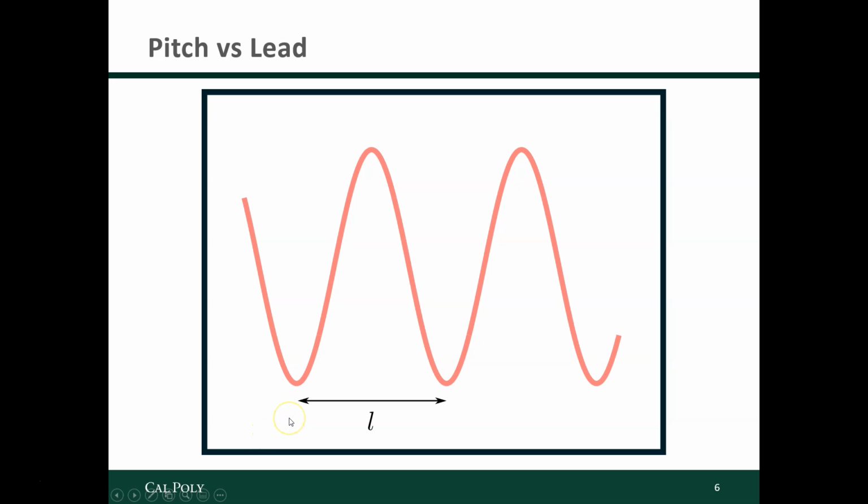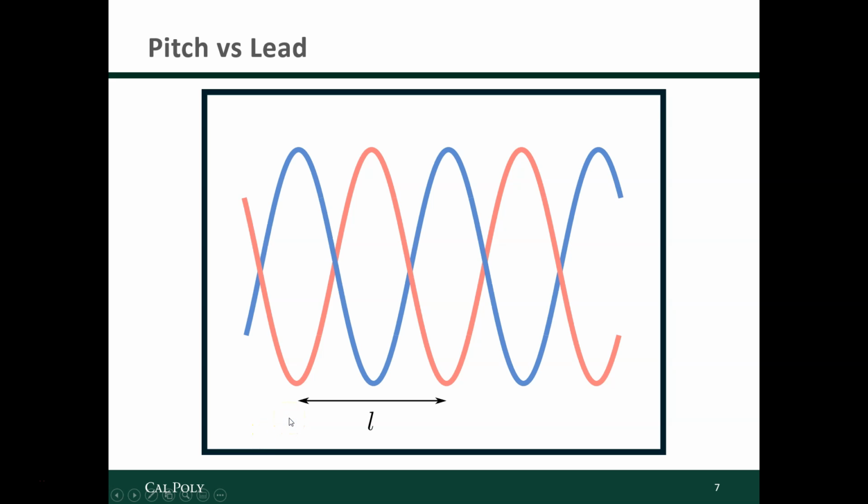If there are multiple starts, let's have a second start here, we have a totally separate thread. If you're on the red thread, you never end up on the blue thread. We can see by the way that they cross right here, the red thread is on top and the blue thread is on the far side of the screw. And over here, the blue thread is closest to us and the red thread is on the other side of the screw. They never touch. We're still going to call the distance between adjacent threads, from the side, the pitch. So you can see that these are conceptually distinct.